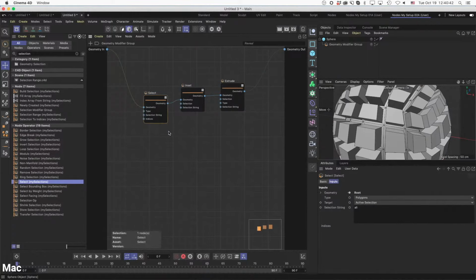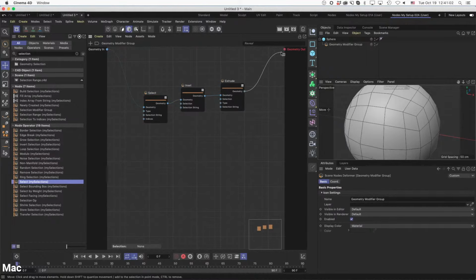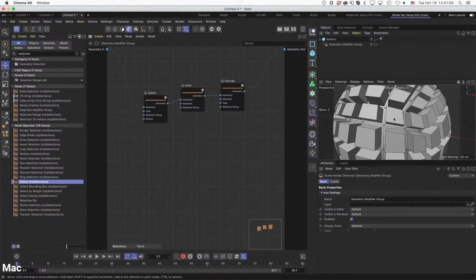So as far as this is concerned, all polygons now retained, because they're in the active selection, are these ones over here. Right? This one, this one, this one, this one, not the little fillets. So now we have our active selection we can work with. And that's why we can take these and extrude only the inner parts.